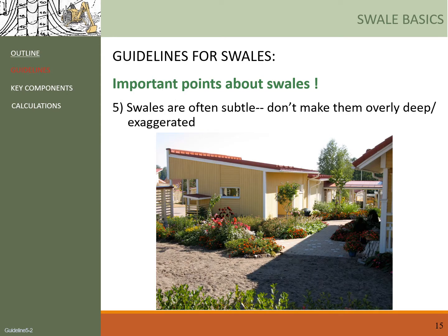Here is another example of a swell. Can you see which way the water is going? It's pretty hard, right? However, you could see the fall of the driveway in the background. So in this case, the swell here is moving downhill from right to left.